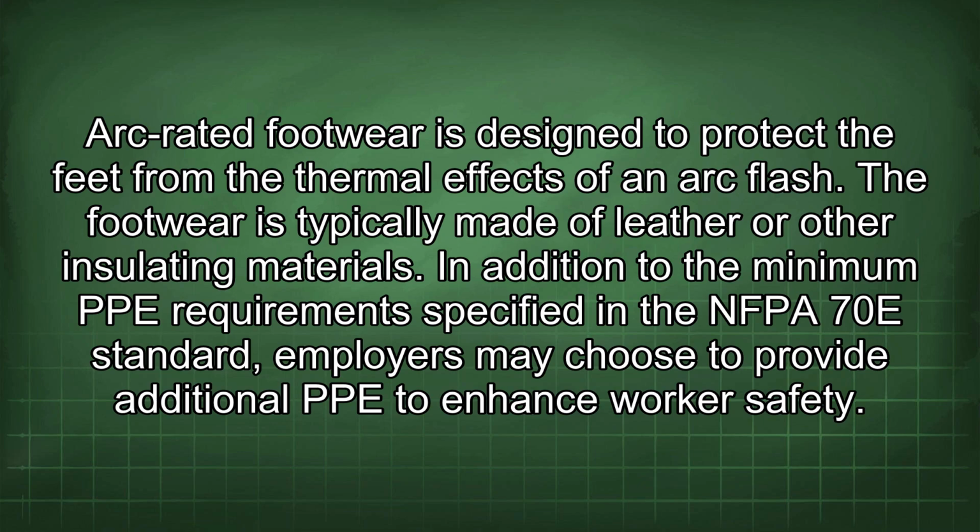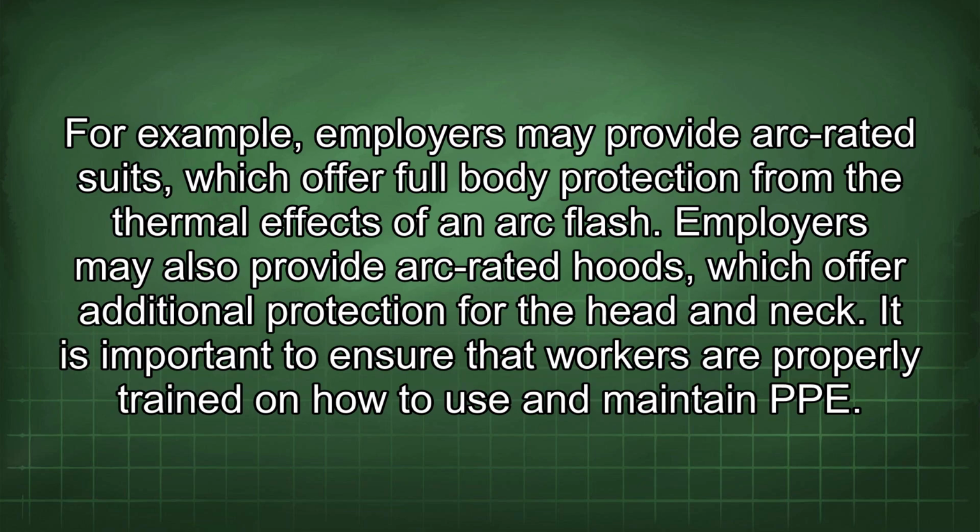In addition to the minimum PPE requirements specified in the NFPA 70E standard, employers may choose to provide additional PPE to enhance worker safety. For example, employers may provide arc-rated suits, which offer full body protection from the thermal effects of an arc flash. Employers may also provide arc-rated hoods, which offer additional protection for the head and neck.